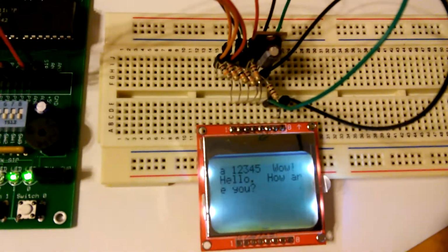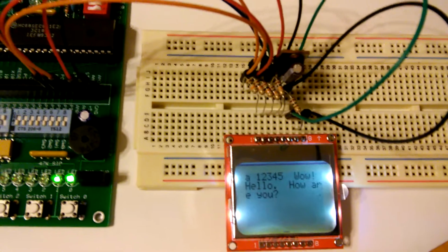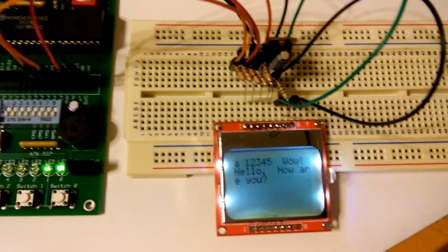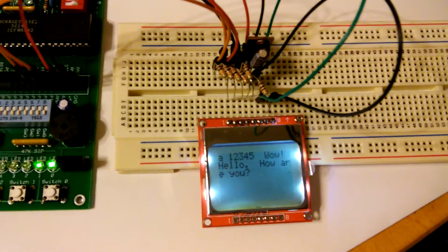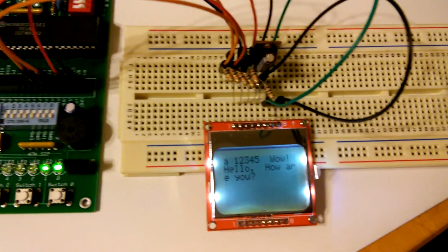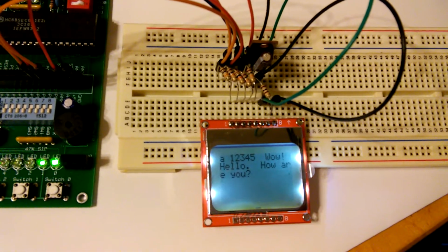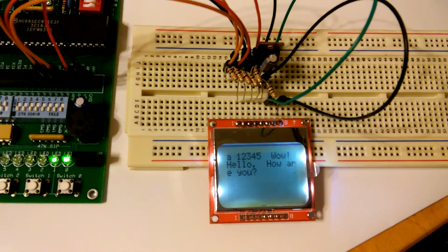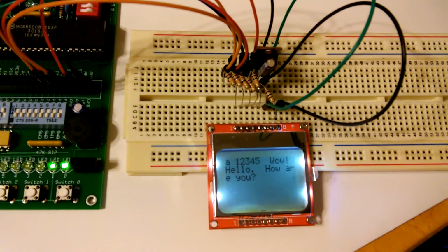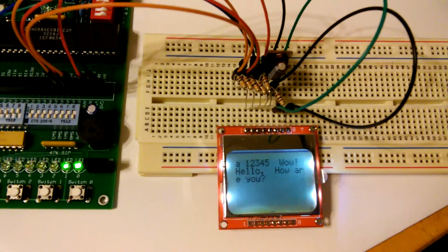Now, the way that the LCD is configured, it's configured pretty much just as an ASCII terminal, in a sense. Basically, it's going to display whatever is coming over the line as an ASCII character, and that is being shown on the screen. It simply keeps on translating each character and putting it on the screen, and once that particular row is all filled up, it drops down to the next row.